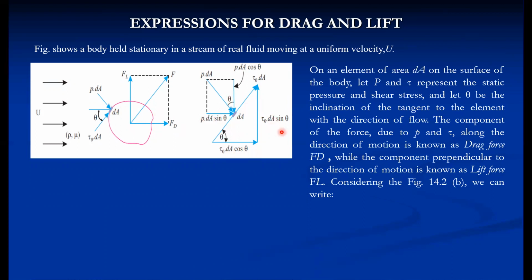the lift forces. So considering the figure, we can write the total drag force as the integral of PdA sin theta. This is for the elementary area. For the entire surface, we do the area integral: integral PdA sin theta plus integral tau dA cos theta. So these are the two components of the drag force.